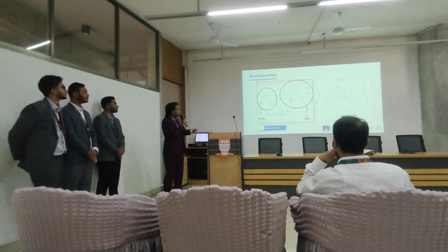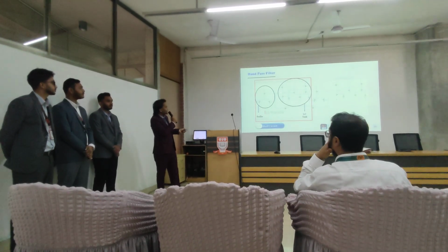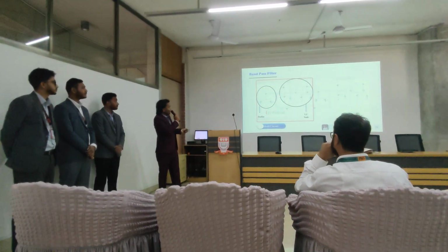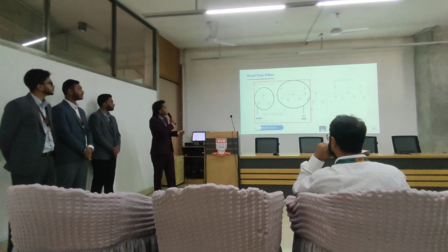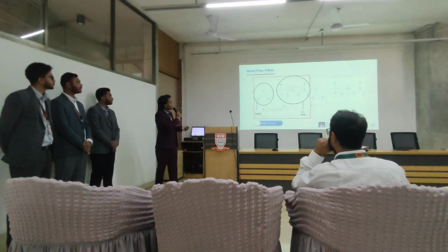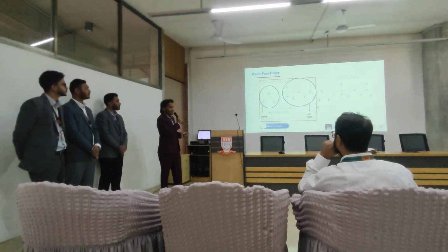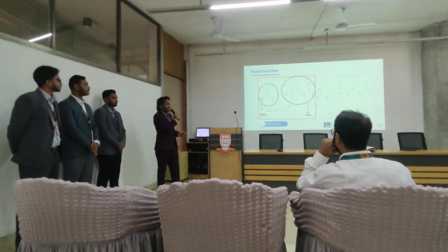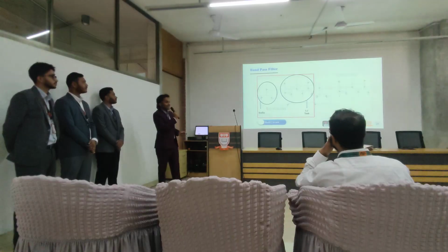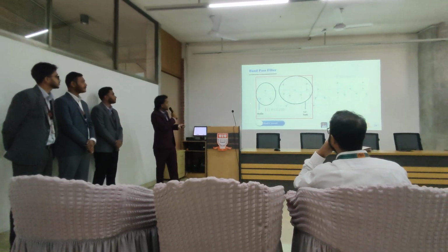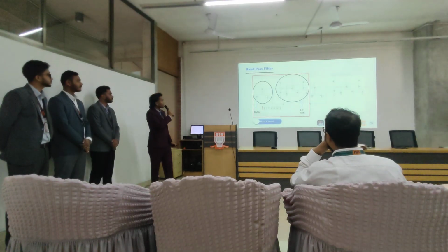the tank. Now for the LC tank to resonate, the capacitance we get from all the parasitic capacitance of all the transistors connected to this central node, and the inductance we get from our gyrator, which uses two transconductors, this differential pair and this common source amplifier, in a negative feedback. Now by delaying and inverting the signal, our gyrator forces the AC current to lag the voltage at this specific node by 90 degrees, which perfectly mimics a real inductor.